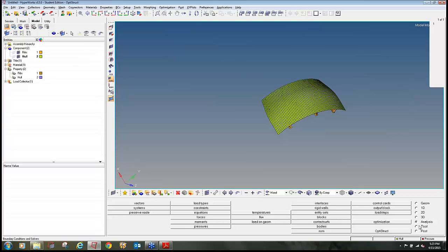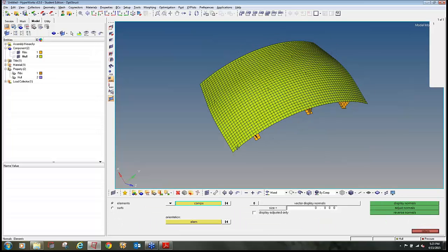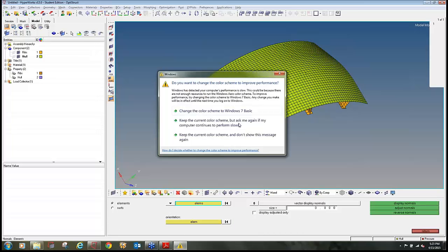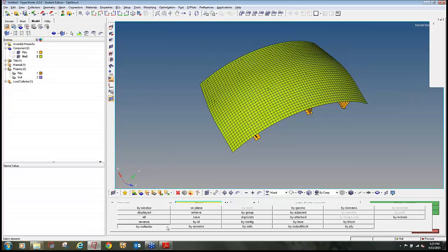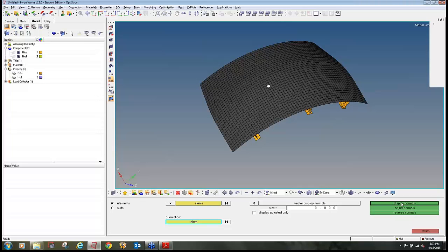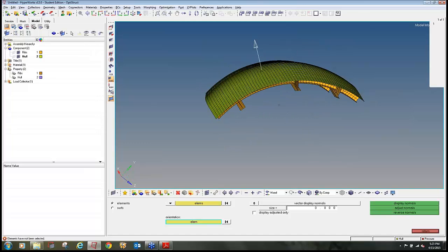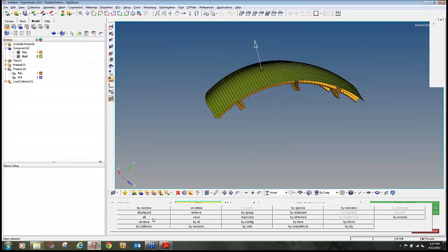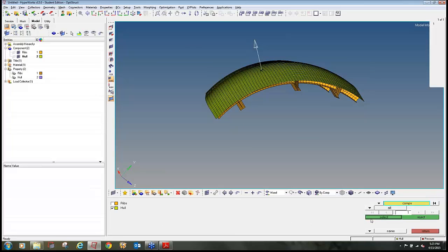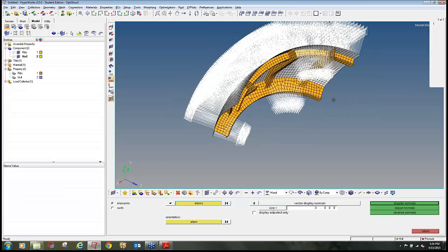So I have to first do this: make the normals of the surfaces equal. So I will select elements by collector, select, orient to this and adjust normals. So if I click on by collector, hull and display normals, still I am getting some of the elements' normals in the opposite direction.